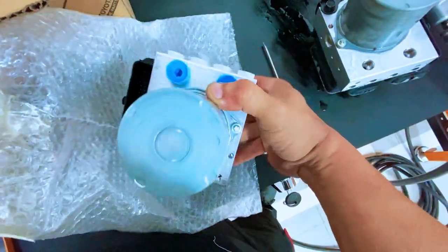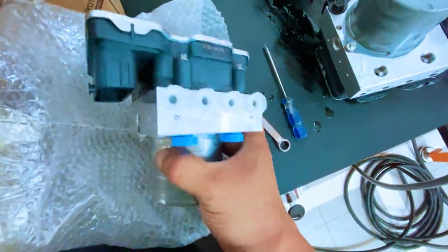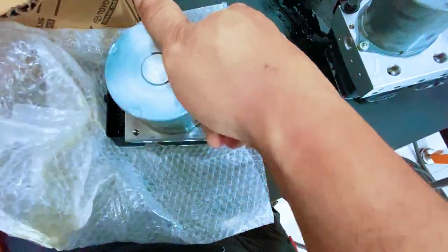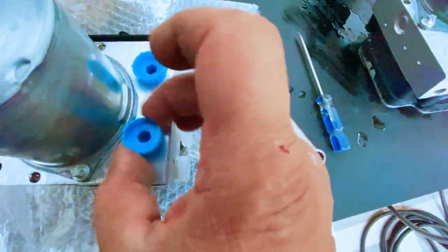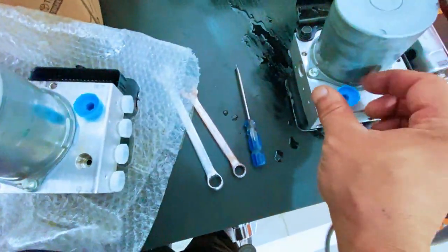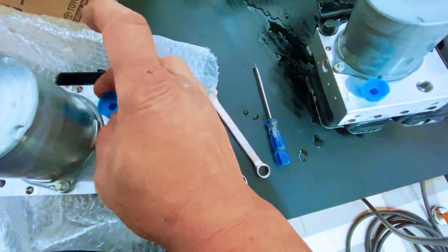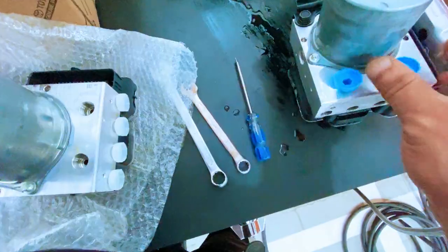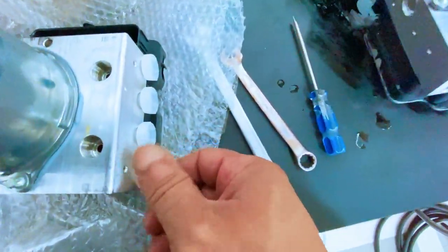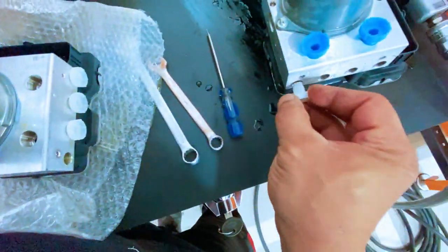DTC and freeze frame check. The next step is to confirm the customer's complaint and check the stored DTCs. If possible, save the freeze frame information before clearing anything. Freeze frame data can tell us what the vehicle was doing when the fault was detected. We should also perform a visual inspection. Check the wiring harnesses. Check the connectors. Check the fuses. Look for damaged wires, loose terminals, corrosion, water intrusion, or signs of previous repairs.